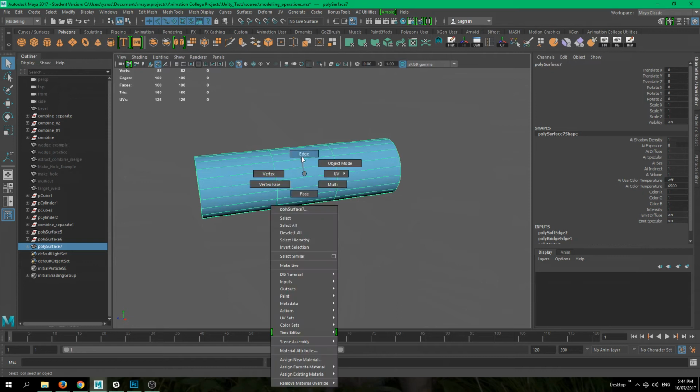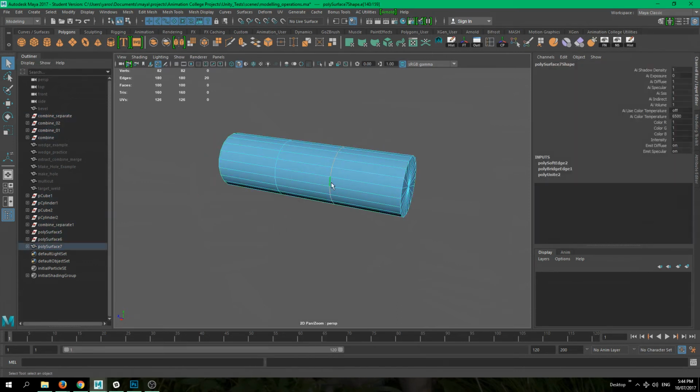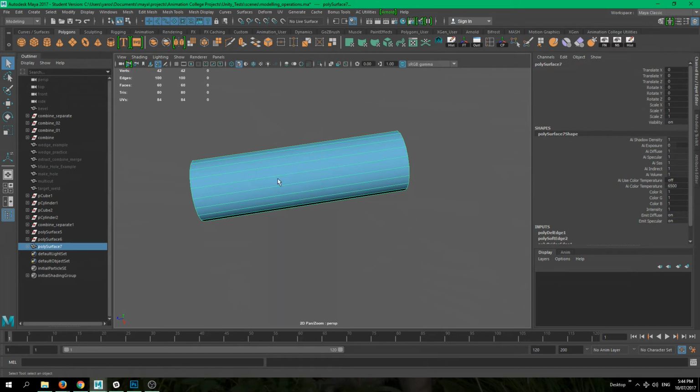You can even go ahead and get rid of the edges you don't need anymore, so if you wanted to get rid of those, you can double click, then with Shift to be able to select something else, double click on this one again, and go Shift right click and delete edge to make sure that you're not getting any floating vertices.